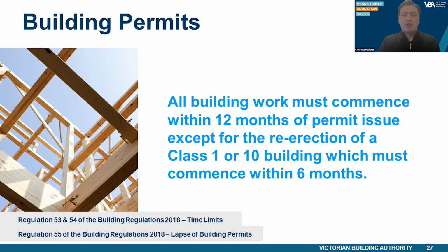If the building work is not commenced or is not completed within the time limits, the building permit will lapse pursuant to Regulation 55. Any building work carried out after a building permit has lapsed will be in breach of the Building Act. An extension of time may be granted by the RBS before the permit lapses.